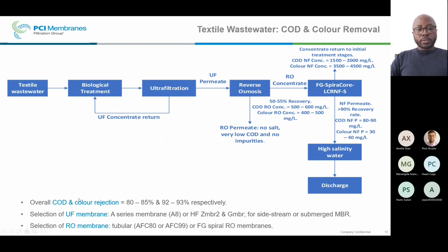So what could be seen from here with regards to COD and color rejection is that we have about 80 to 85% COD rejection when talking about the rejection rate, comparing the inlet from the concentrate of the reverse osmosis to the outlet in the nanofiltration.